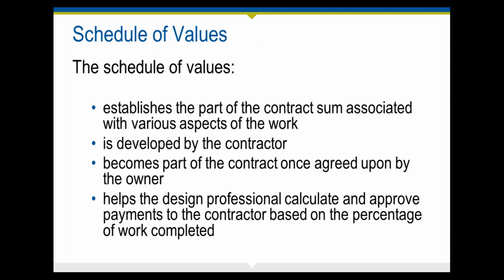For you to do payment applications, one thing that you need from the contractor to make this a meaningful exercise is to get the schedule of values. That is typically required of the contractor and establishes a part of the contract sum associated with various parts of the work. So if you are certifying the pay apps that are being developed by the contractor, you need to know what the various parts are supposed to cost, so that based on the percent complete, you can say, okay, well, this wall is 50% done. We can pay 50% of this schedule.